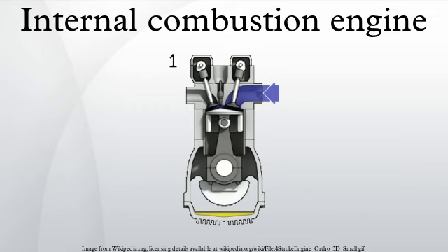Two-stroke spark ignition engine. In a 2-stroke SI engine, a cycle is completed in 2 strokes of a piston or 1 complete revolution of a crankshaft. In this engine the intake and exhaust strokes are eliminated and ports are used instead of valves. In this cycle, the gasoline is mixed with lubricant oil, resulting in a simpler, but more environmentally damaging system, as the excess oils do not burn and are left as a residue.